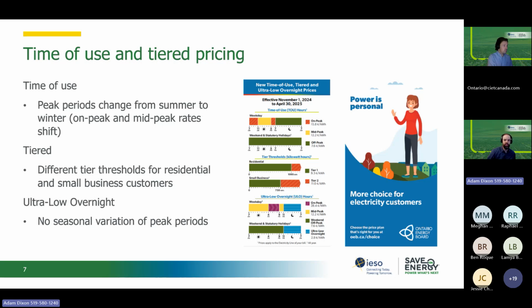With this rate structure, when you're evaluating projects, you have to make an estimation of, first of all, how much you use up front. If you're in and around the break point where the price changes, you may need to do a bit more of a calculation. But if you're below it or above it, you want to pick from the higher bucket to calculate your energy savings. So if you're at 2,000 kilowatt hours and you're putting in a few LED lights, you can say the savings are going to be at that 11 cents per kilowatt hour. So let's just think about that.